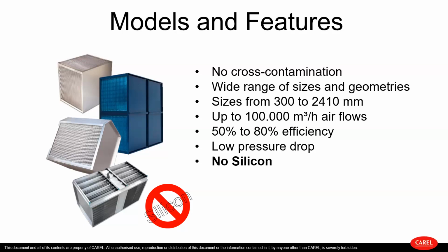Because there is a kind of compromise between the efficiency, so the characteristic of the plate heat exchanger, and the maintenance to keep it clean in order to have the best performance out of it. And then we also have the pressure drop, of course, which is a characteristic of a plate heat exchanger, which is the energy lost by the air running through the heat exchanger, which could be between 100 and 200 Pascal, more or less.